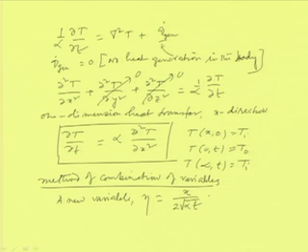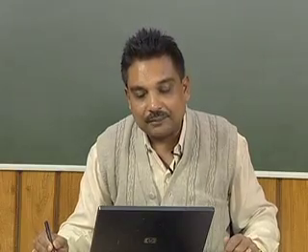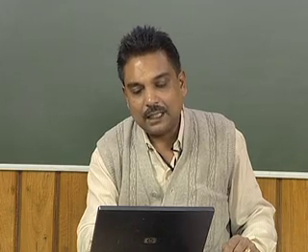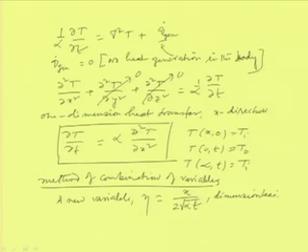So, this is one independent variable that is being taken, and interestingly we can see that eta is dimensionless. We have taken a new independent variable for this solution, eta, which is a dimensionless quantity, by coupling the two independent variables x and t, where t is the time. The unit of alpha is meter square per second, and the unit of time is second. So, the unit of root over alpha t is only meter, and the unit of x is meter. So, finally, it is becoming unitless. This is a dimensionless quantity.